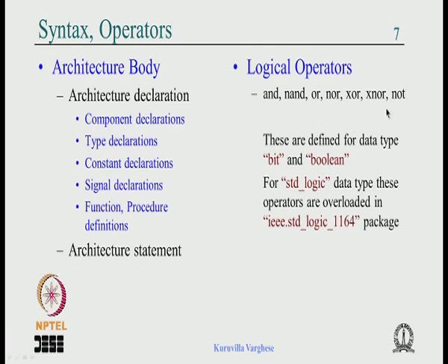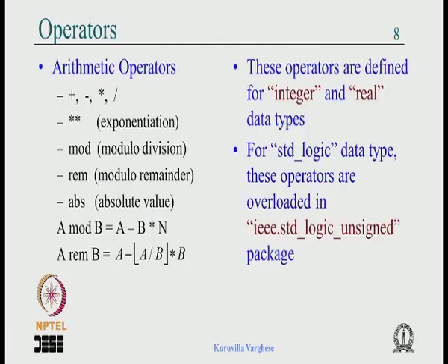These are the logic operators which are defined for bit, but in the standard logic 1164 package they are overloaded for the standard logic data type. And you have arithmetic operators, and there is a mod and rem, and we have seen the difference. This rem works with negative numbers, the real mod of computer science. Once again, this is defined for integer and float, and for standard logic these operators are overloaded in this particular package, std_logic_unsigned.